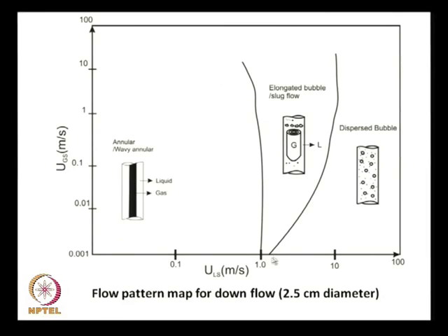Definitely, transitions do not occur under fixed curve conditions. There is a range under which annular flow gradually gives way to slug flow, and slug flow gradually gives way to bubbly flow. So, in order to predict these ranges, experimental flow pattern maps are fine, but from mathematical equations you cannot get a range, you can just get a curve. So, these artificial soft computing techniques can be useful.